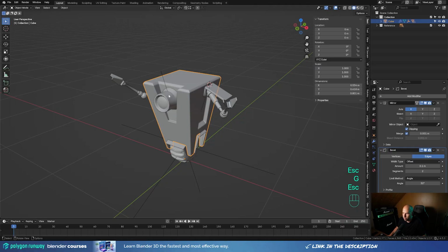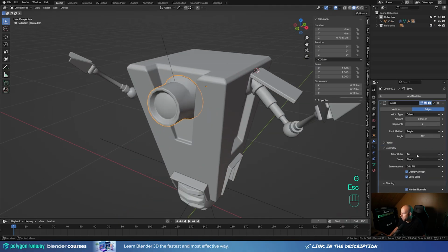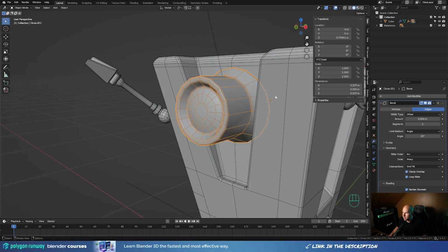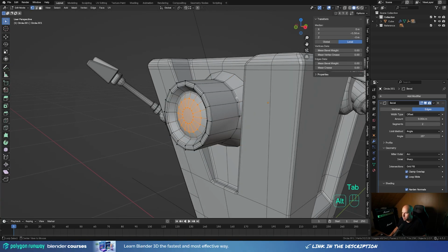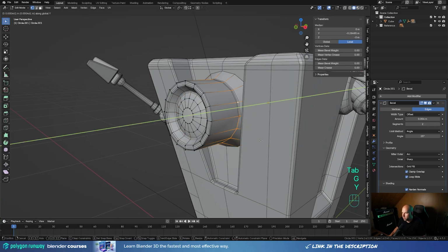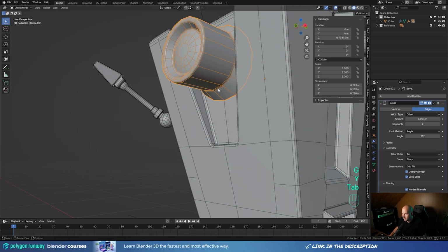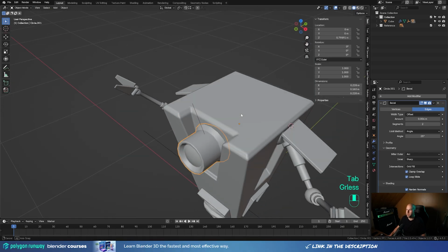The claptrap can be moved. Here we'll adjust a little bit of that angle again. So what we can do is do 25 degrees and make it a little bit sharper. So tab into the edit mode, alt click here, press G then Y, and we'll just move it back until we hit all of these like that, and we have some bevel modifier happening there.